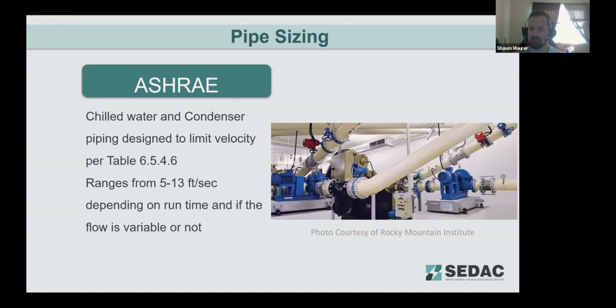Limiting the bends and minimizing the equivalent pipe length is going to further reduce the pressure drop, which may enable smaller pumps to be used as well. In the photo that we've shown here, in most chiller plants you see an optimized space design where you've got 90-degree bends in the piping to limit the footprint of chiller systems. Here they've opted for 45-degree bends or less. Looks like these may be even 30-degree bends. So they're limiting again that frictional impact that those fittings have on the flow of that fluid.